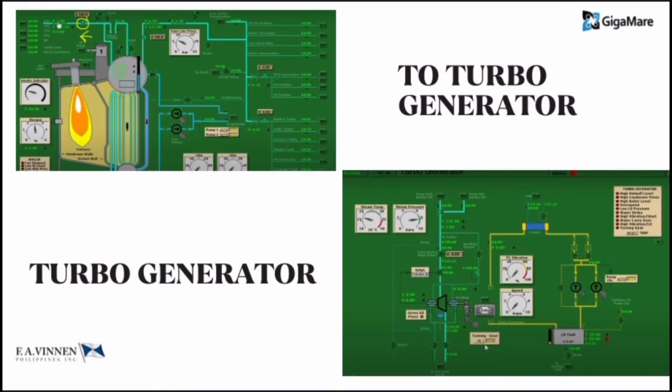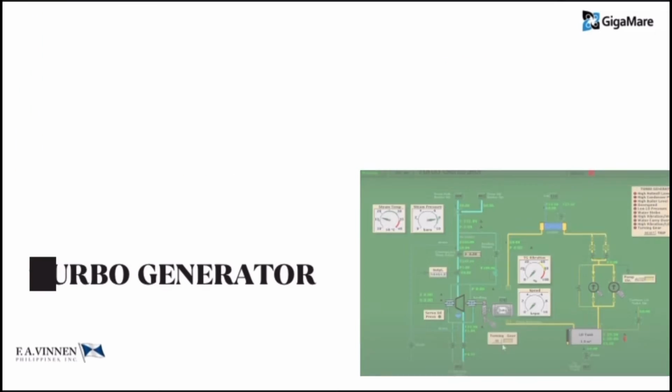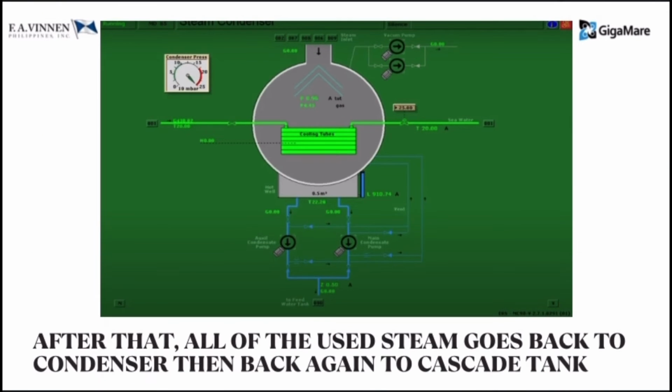Again, we can see here in the diagram that it has a main steam valve going to the turbo generator because it also consumes superheated steam needed in order to produce electricity. And after the used steam goes through the turbo generator, it will go to a condenser where the cooling medium is seawater to convert steam into condensate liquid.